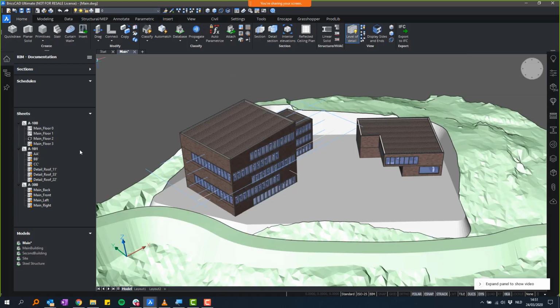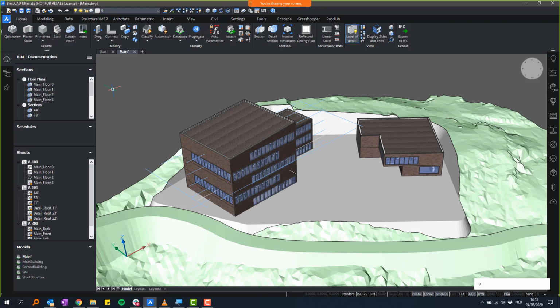And you can see when I have my structure browser, my project browser here, what I can see here is all of my section planes. So you see here these blue lines. These are the same kind of sections that we've been using earlier to just section through our building while modeling, for instance. These same section planes can be used to generate 2D plans and elevation sections, things like this. And they're listed here.